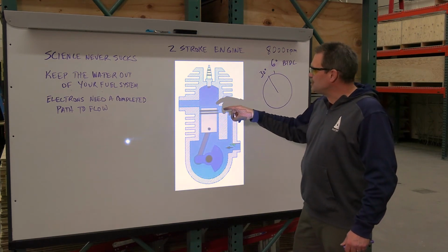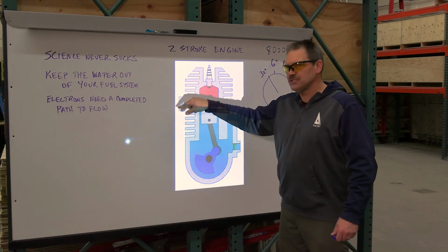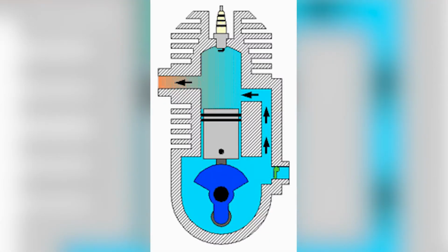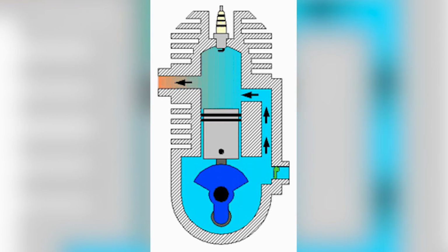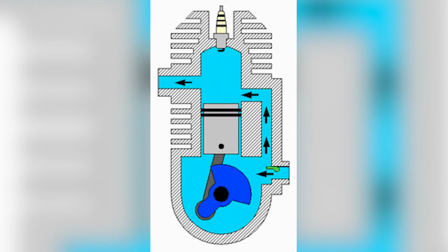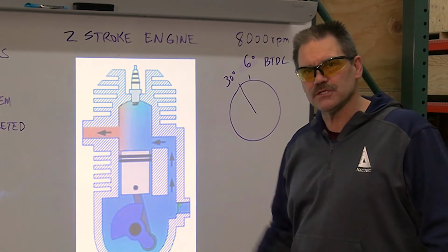A lot of the newer machines today actually have a valve in the exhaust here. They have found that as the volumetric efficiency changes, in other words as the engine changes RPMs, the engine will get rid of the exhaust a lot more efficiently if you change the size of the hole going to the exhaust pipe.